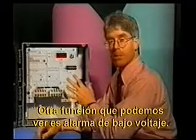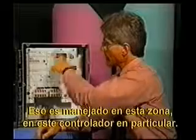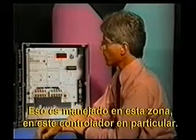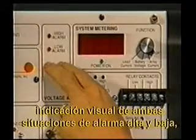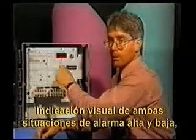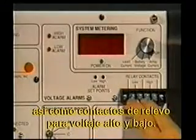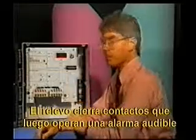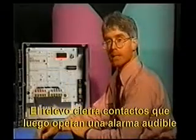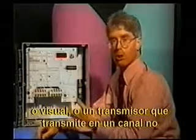Some of the other functions that we might look at is low voltage alarm. That's handled in this area of this particular controller. The alarm points are adjustable. We have a visual indication of both a high and a low alarm situation. And we have relay contacts available both for the low voltage and high voltage situation. The relay would be involved in closing contacts, which would then perhaps operate an audible or visual alarm.